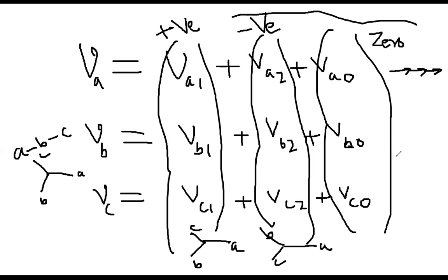And even though it is not a Y connected system, it could be a delta connected system, but still this zero sequence component current will flow through each coil of the delta system. Consequently, over time, the coils will be overheated and may be damaged. So that's why, with respect to positive sequence, negative sequence and zero sequence are not desired. So this is pretty interesting. I'm just telling you the significance of the phase sequence and how we can analyze an unbalanced system.